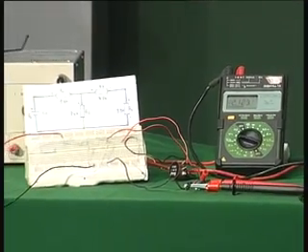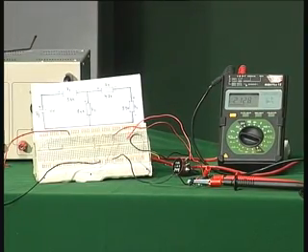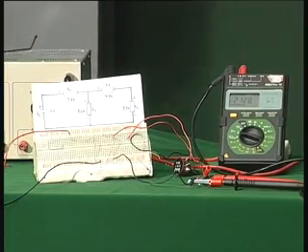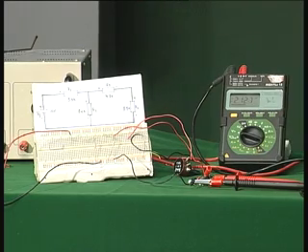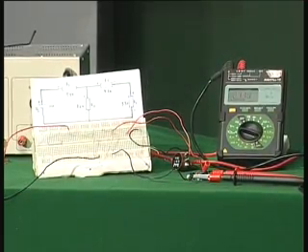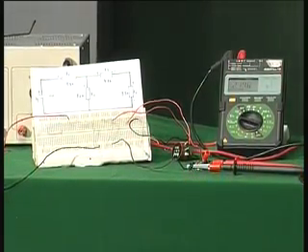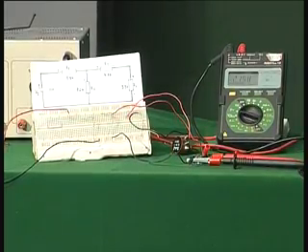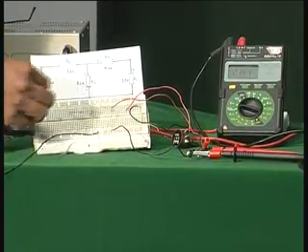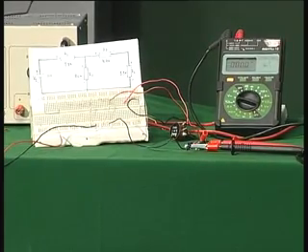Now what we will see is, we have calculated the V Thevenin, we have calculated the R Thevenin. Therefore now I am going to introduce the V Thevenin, R Thevenin only, and put the load resistance and measure what is the output voltage. If we again get 2.1, then we have solved the circuit. So let us now try to do that. What I am going to do now is take this power supply out and set here 6.